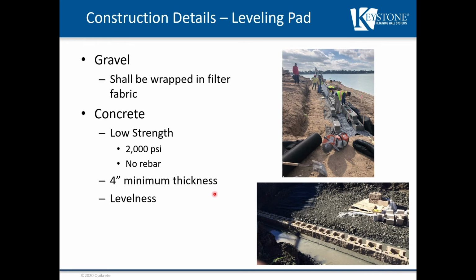It can be a concrete leveling pad. You might find that it's a little bit easier in water applications, or in certain applications where you want to protect against additional erosion or potential movement and just quick setting. Just get the concrete leveling pad in and go, because you need to work a little bit quicker. Is another application where you might consider using a low strength unreinforced concrete leveling pad.